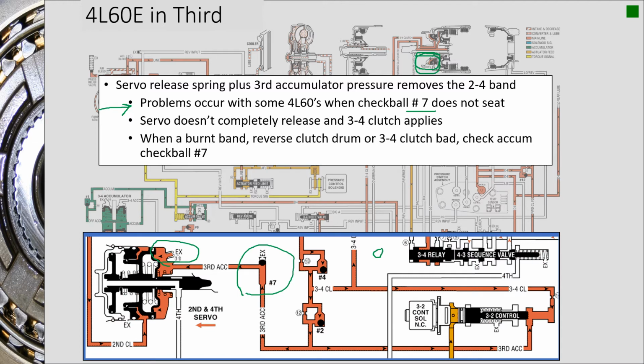And heck, you can leak a little bit around the servo pin where it goes through the case. There's potential for leakage in a bunch of different places. If all these little leaks start adding up and come close to the size of the actual orifice, then you're in trouble, because you're not going to be able to maintain pressure on the other side of the orifice if all the leaks end up being bigger than the hole itself.